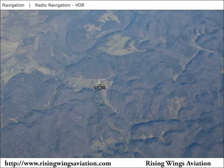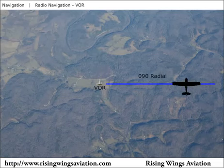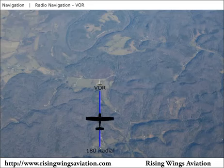If the equipment in the airplane says the airplane is on the 360 degree radial, then the airplane is north of the VOR. An airplane on the 90 radial is east, while one on the 180 degree radial is due south of the station. Since pilots rely on the compass for directional guidance, the radials transmitted by VORs are aligned with magnetic north.